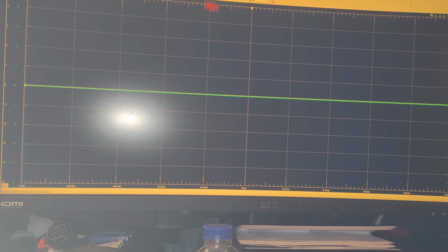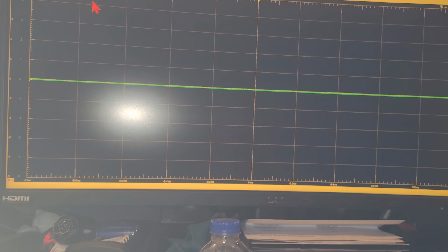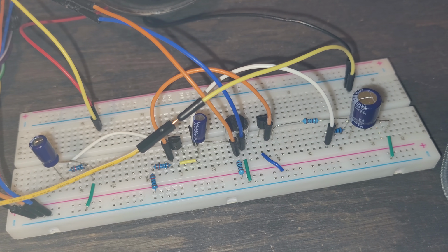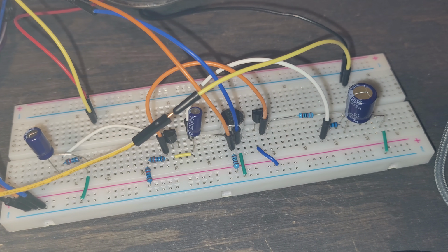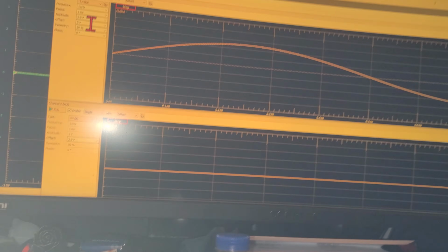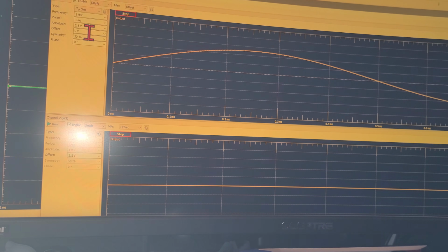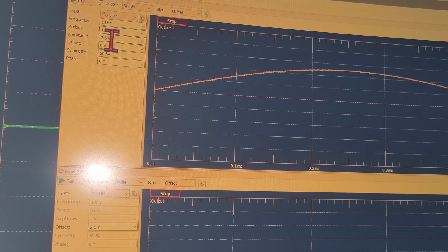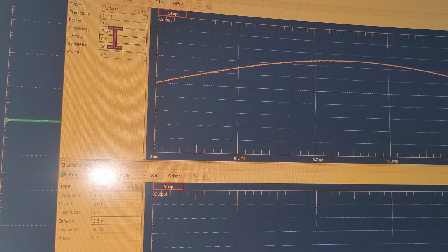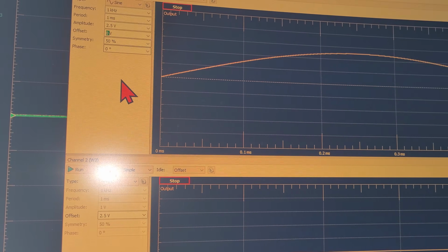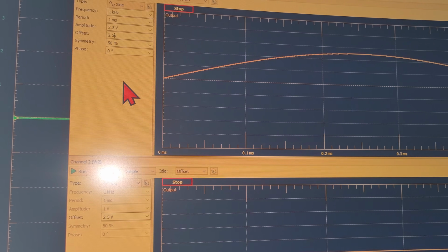The blue line is on top here. If we run it like this, it's actually going to give us an overvoltage protection. I believe that's to do with our waveform generator. Currently the waveform generator is at 2.5 volts for an amplitude and a 0 volt offset. So I think the reason why is because this needs to be at 2.5 volts.